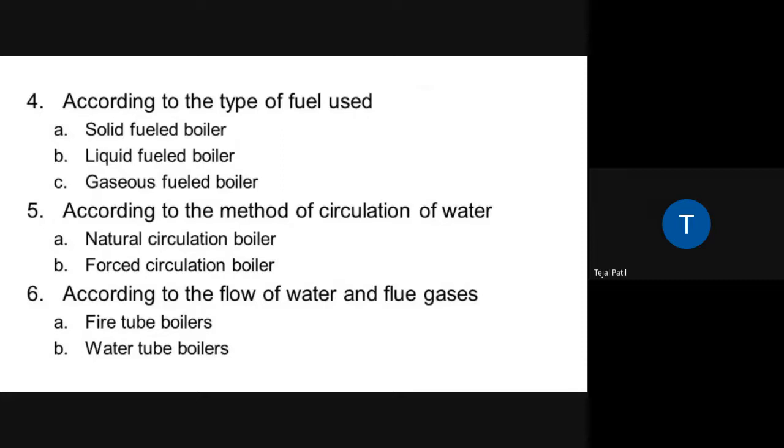You can take a transparent glass with water in it. Make sure that water is the warmer or hotter one, and then take another small glass and color the water inside it, and that water should be the colder one. If you put that cold water inside the hot water, you will find that it goes to the bottom level. Why? Because of the density. So that is the concept used in natural circulation. Forced circulation, simply a pump is used.